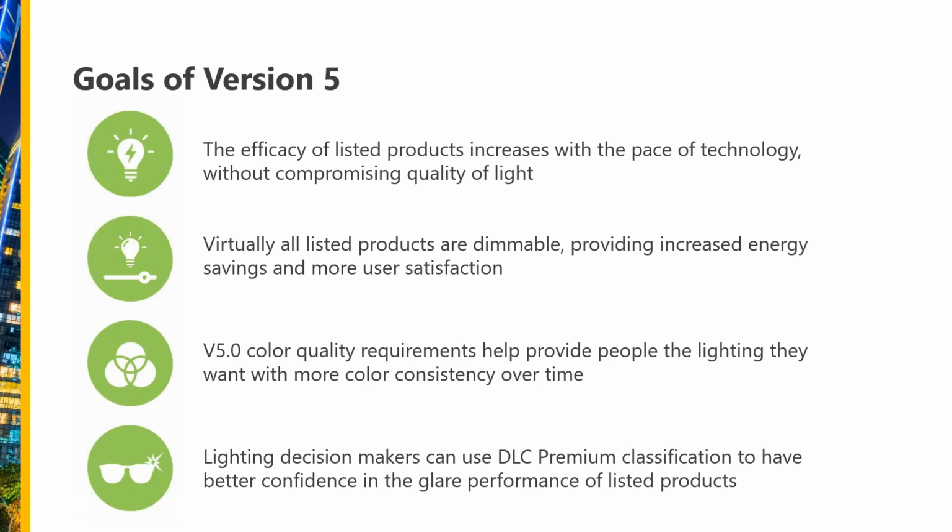These new enhancements to the DLC color requirements will help provide people with the lighting they want for their application and provide greater color consistency over time. And this is an important issue with LED lighting. And finally, we've revised DLC Premium's classification to include additional criteria for glare performance. This will help ensure that products that achieve higher efficacy of premium do not do so by compromising glare control. So the users of DLC Premium lighting will have better confidence in the glare performance of these products.